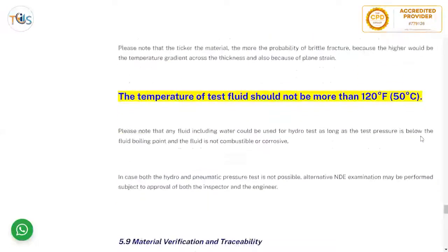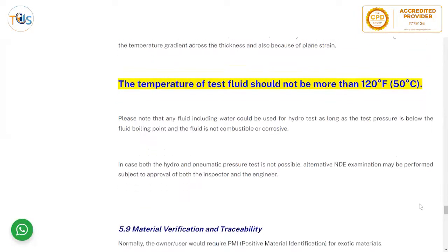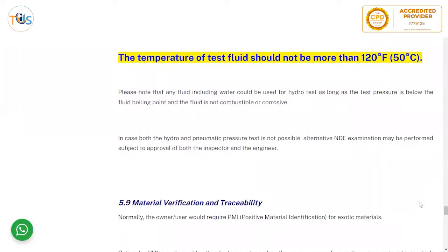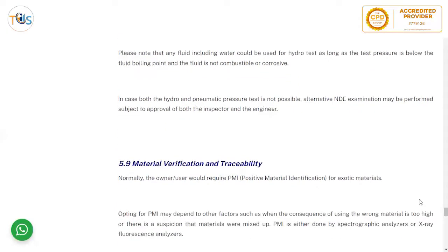The temperature of test fluid should not be more than 120 degrees Fahrenheit. Please note that any fluid, including water, could be used for hydro test as long as the test pressure is below the fluid boiling point and the fluid is not combustible or corrosive.